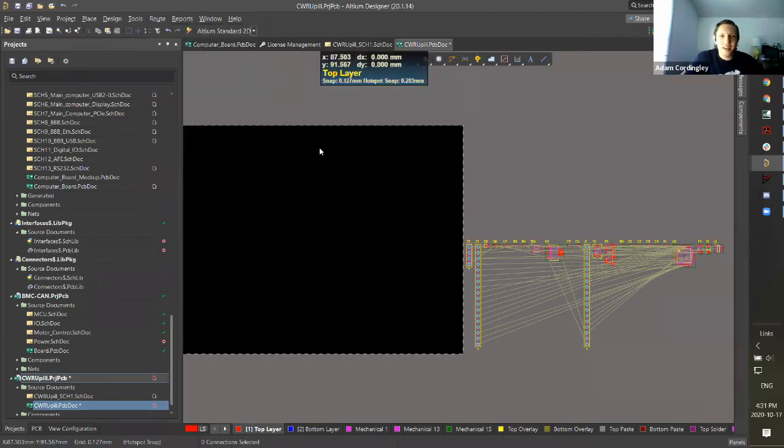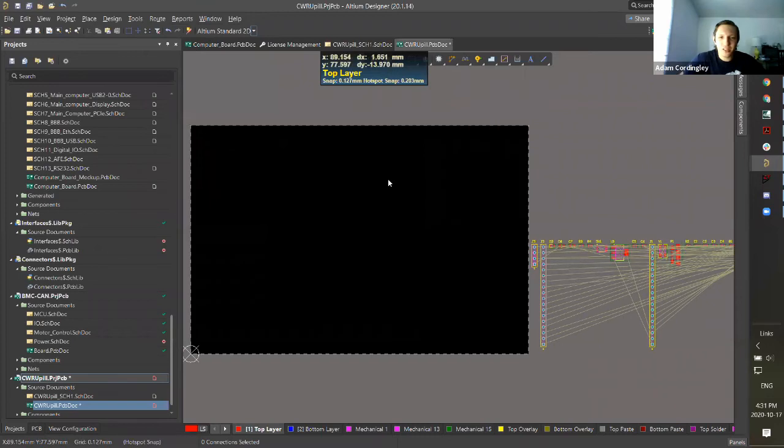But I also think that the results will be obvious when you've used an auto router. And I think there are very specific cases where auto routing is useful, mostly which have to do with thousands of pins, and when you're doing pin swapping between your different GPIO banks and very complex designs that demand using an auto router. There's a time and a place for the auto router.